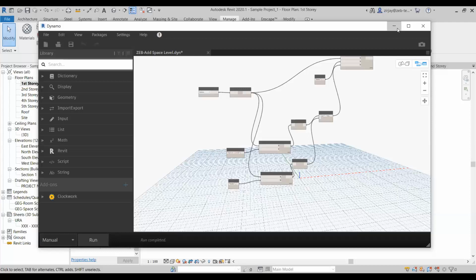Okay, so I'll start that again. Go to File, Export, gbxml. Use space volumes. Yes. And first thing we need to do is change the location to whatever you want. So in this case, I want Singapore. I'll search for it, then click on this, so that will set it to Singapore. And then I'll click OK.